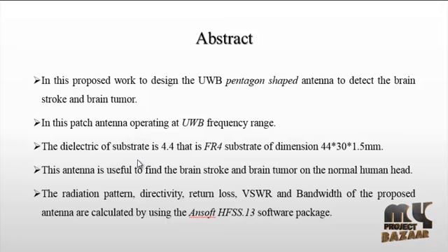For the dielectric substrate, we are using the FR4 substrate. FR4 is one type of substrate material, which is simple and easy to use. The dielectric constant is 4.4 and the dimension of the substrate is 44 by 30. The height of the substrate is 1.5 mm. All the dimensions are defined in mm only.